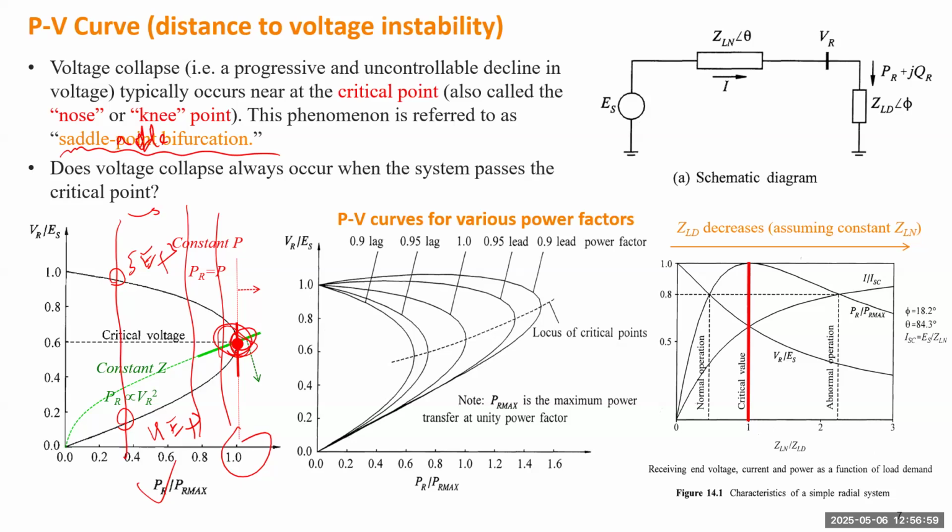At the beginning of this lecture, we'll talk about another useful tool. This PV curve is good to study how far you're away from the boundary of stability for your current loading condition. You can draw such curves for many different power factors. If you determine the power factor for your system and increase the load for one area or at one bus without changing the power factor, the voltage will change according to that specific PV curve.